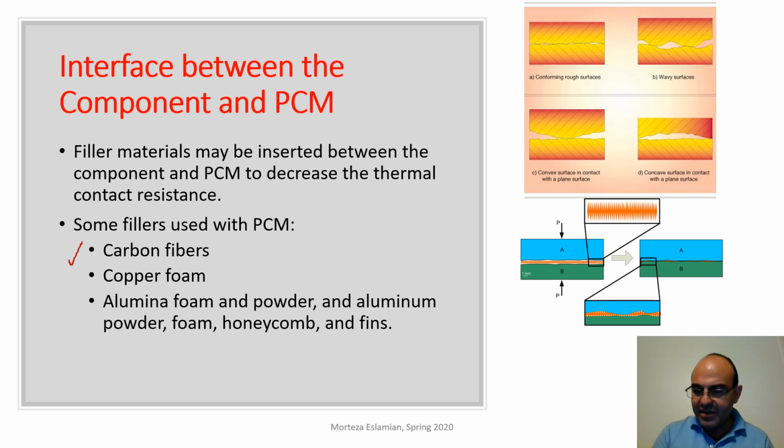When these fillers are inserted between the two different materials, they fill the gaps, so the thermal contact resistance is reduced and therefore the heat transfer rate increases. Without these fillers, if the thermal contact resistance is high, the heat transfer rate will substantially drop and the thermal solution may not work.